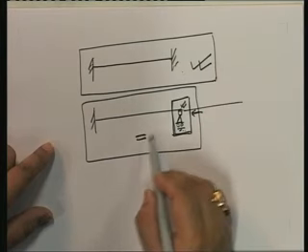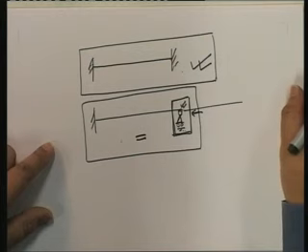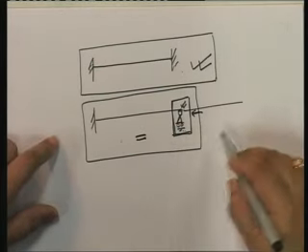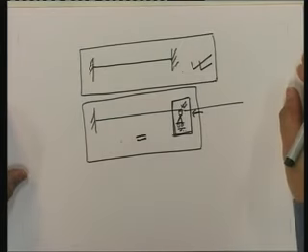And today I have shown you how the force deformation relationship is different for this one. I hope today's lecture has made it clear to you that even in the displacement method, you can bring in simplifications to reduce some of the equilibrium equations and degrees of freedom, and thereby reduce the equilibrium conditions that you need to specify.